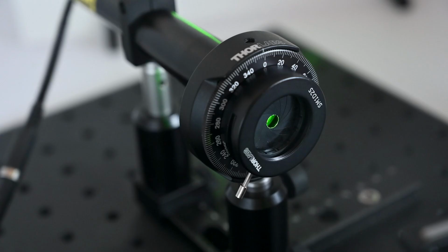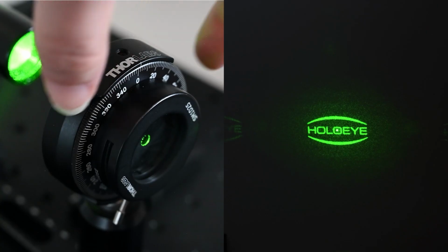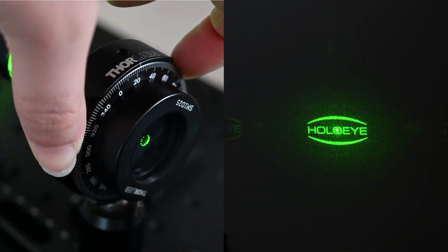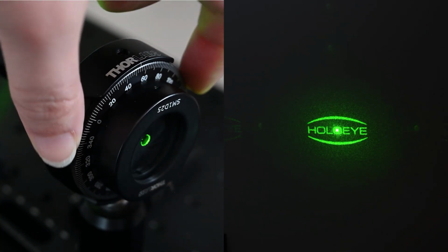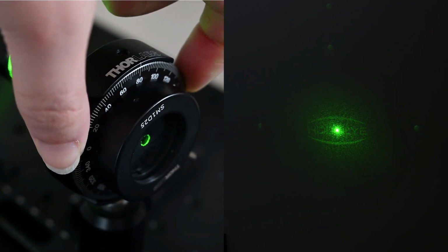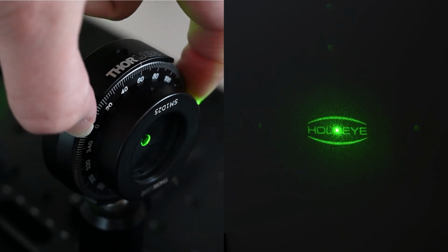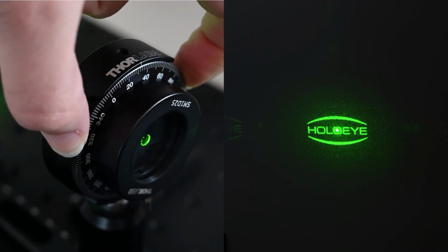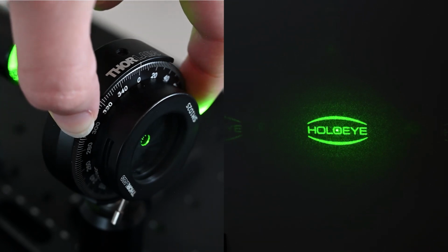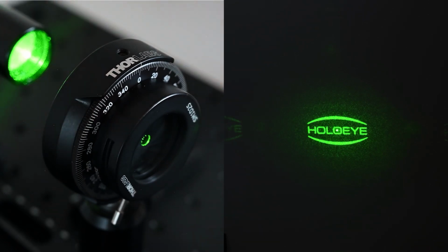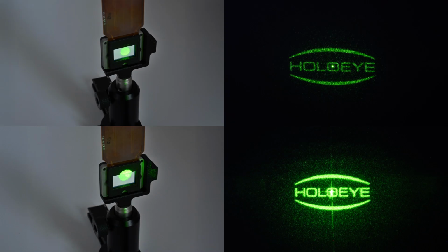To use the SLM for phase-only modulation, the incident polarization has to be along the director axis of the LC molecules. For most HOLOEYE SLMs, it is along the long display axis. Any other incident polarization would lead to undesired cross-modulation between phase and amplitude modulation. Some HOLOEYE SLMs have an aperture on the display. If you illuminate the aperture, you get a visible noise at the 0th order. Please avoid illuminating the aperture. The SLM is now properly configured.